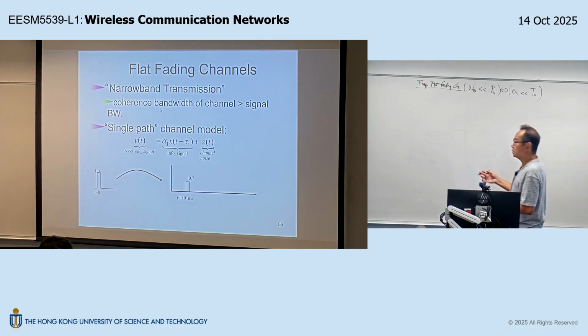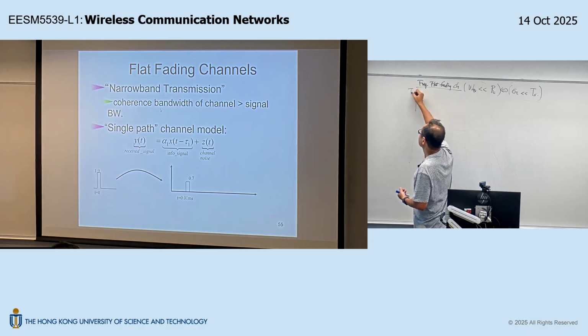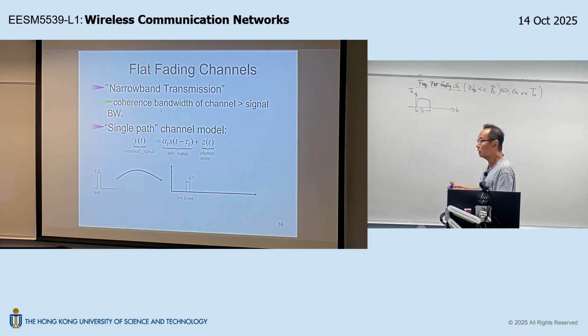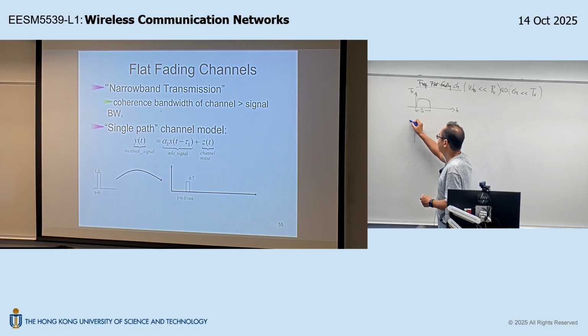So let's try to visualize the time domain process. At the transmitter, let's say you transmit a symbol with a duration Ts. Now, in the physical channel, you still have multipath. You may have the first path giving you a certain delay, a second path giving you a certain delay with a different response, all the way to, let's say, 1,000 paths. But this is the delay spread, right?